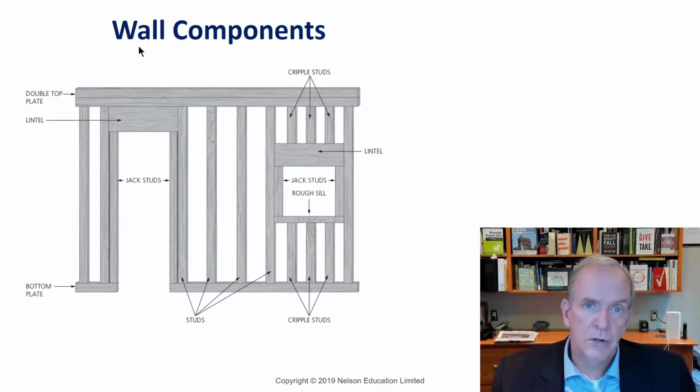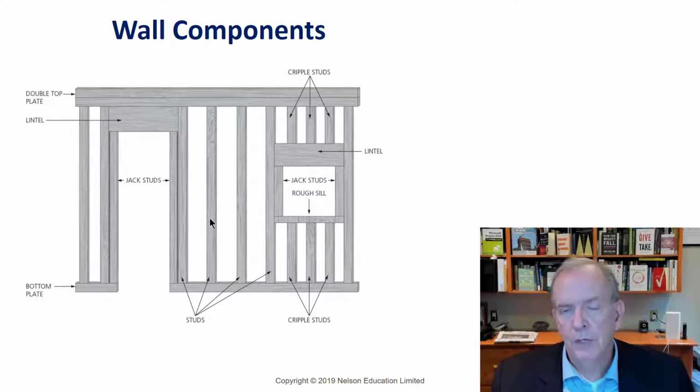So there's a lot of considerations when we're talking about the design of the components, the beam systems, and the spacing of the studs that goes into wall framing. Typical spacing for wall studs is, in building code terms, 400 millimeters, which is 16 inches on center, pretty close.